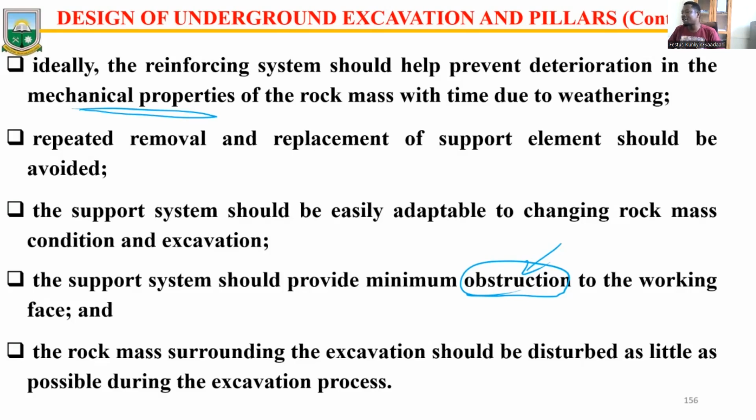Then the rock mass surrounding the excavation should be disturbed as little as possible during the excavation process. So for example, even with the rock bolt, because you have installed rock bolts doesn't mean you should go about doing activities that can tamper with the integrity of the bolting you have done.